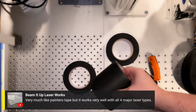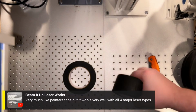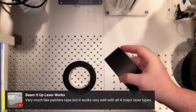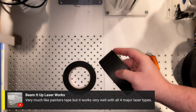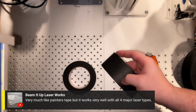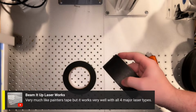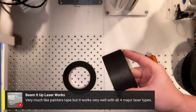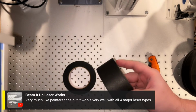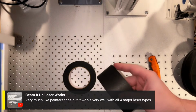So pretty good stuff. This is where Anthony's saying it's very much like painter's tape, but, and this is kind of where he had to hunt to find the right stuff, this specific tape works really well with all 4 major laser types. I definitely get what he's saying there. I've bought painter's tape, plenty of it in my business lifetime, and some of it will work great on CO2, especially the black. I'll get a nice bright white mark on CO2, and then I'll take it over to the fiber and mark it, and it's black on black, which is impossible. So being able to use this with all 4 major laser types is one of the key selling points here.